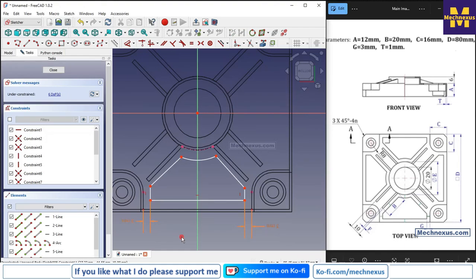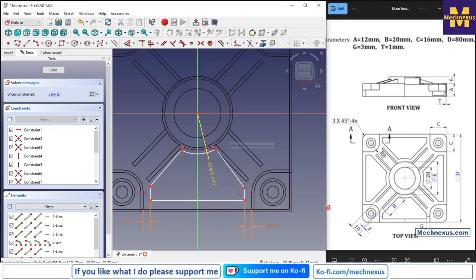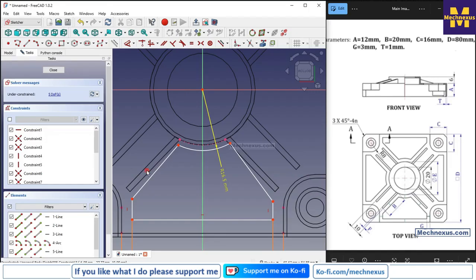And now let's define the radius. Select a smart dimension, and this radius is of 16.5. And here we will project these rib edges on both the side, and we will add a parallel relation. Select this and this and add a parallel relation.